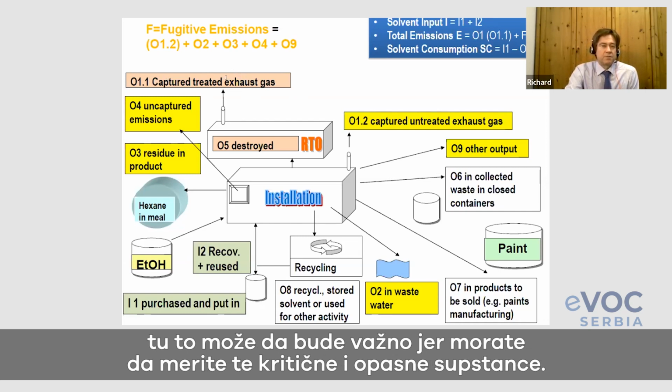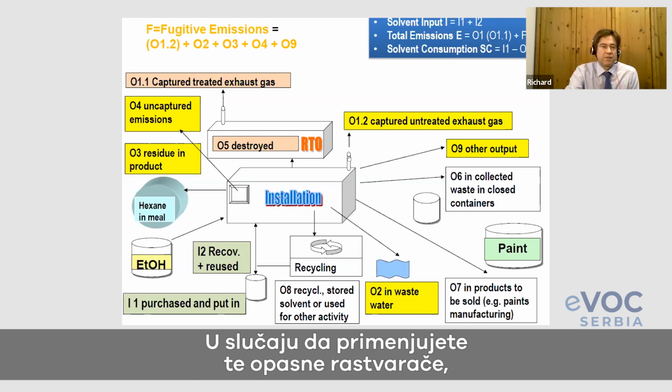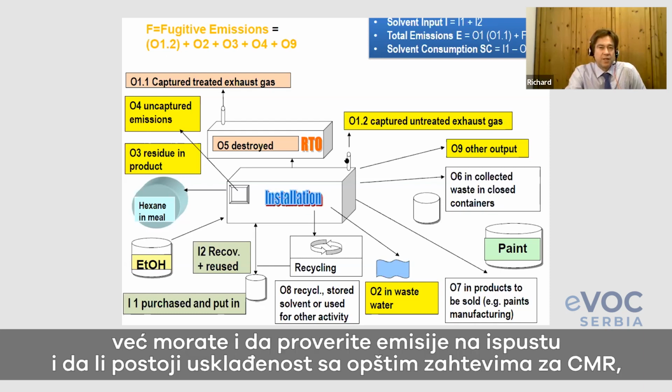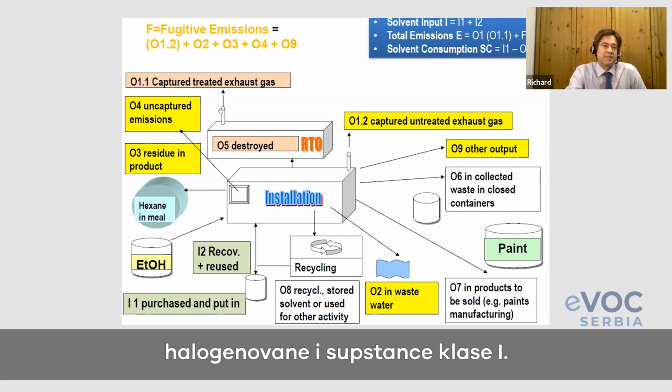That one can be important because here you have to measure those critical and hazardous substances. So in case you apply such hazardous solvents, you have not only to look at the total emission limit value, you have to check the stack emissions, and you have to check the compliance with these general requirements on CMR, on class 1 substances or halogenated pollutants.